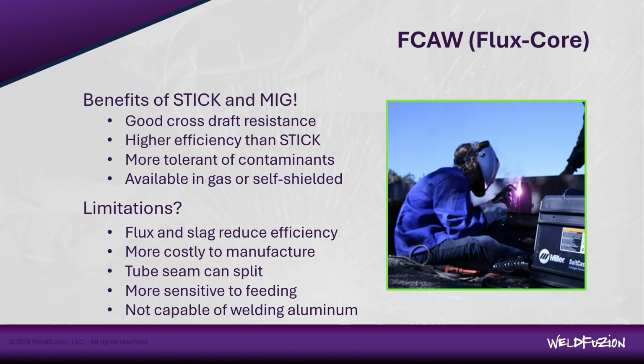But like I mentioned, flux and slag reduce efficiency, and it must be removed. So that takes time, and it adds some extra steps. And if you've ever worked in a shop that did flux core, you kind of hear that crunch, crunch, crunch every time you walk around, as you're walking around all day, because you're hearing that slag. And that's the same with submerged arc welding, which we'll talk about in a bit too.